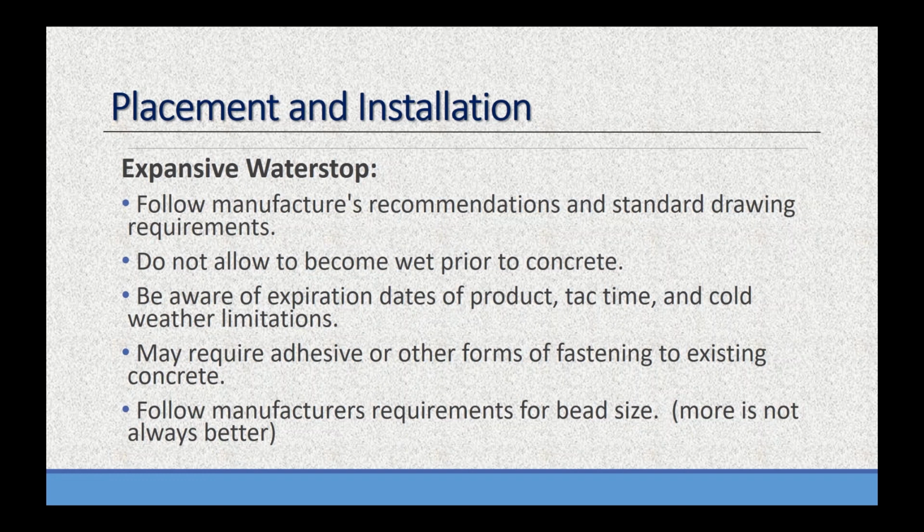Some of these expansive water stops may require adhesive or other forms of fastening to existing concrete. You might put some hydrophilic paste down. You might be using concrete nails. The key thing, it has to be in place and unmovable prior to the pour. Again, and additionally, and this is critical, follow the manufacturer's requirement for bead size. More is not always better for bead size. You have to be very cognizant of the concrete coverage based off the product that you're going to use and not exceed the bead size recommended by the manufacturer.